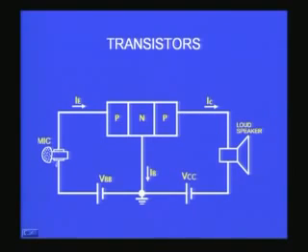Now when I speak into the mic, what is going to happen? It is going to generate some electrical pulses, a fluctuating AC voltage due to the vibration of the diaphragm and things like that. So there is a small AC voltage generated, and the effect of this AC voltage is to modify the constant VBB voltage that I have connected between the base and the emitter by a small variation. This will correspond to a small variation of a similar type in the emitter current. So the amount of electrons emitted into the base will also fluctuate in a similar fashion. But because this is a forward bias junction, a large number of electrons will be fluctuating in this direction.